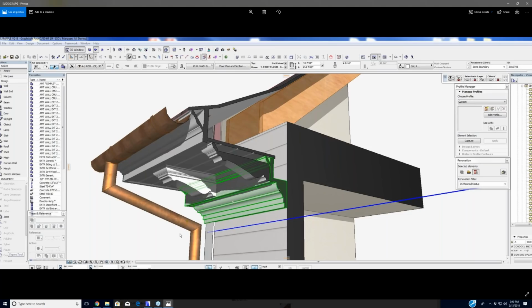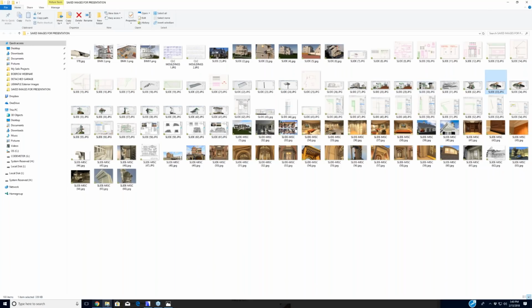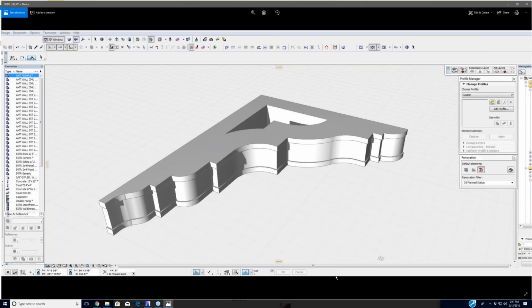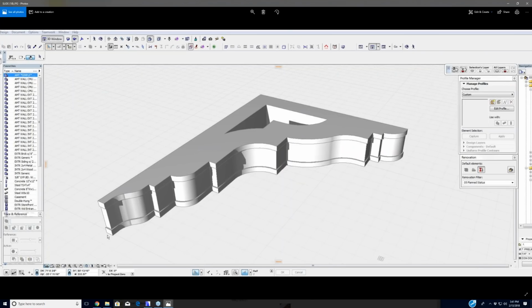What Eric asked, I think, is whether I have any foundation drawings. But remember that you can call up anything that's in the 3D window and save it as a BIMX file. This might be a big bracket. I could save that as a BIMX file and send that over to the builder. He can rotate it, click anywhere he wants and get the dimensions. I can also print this one-to-one, which is what I did, and they use that as the template.